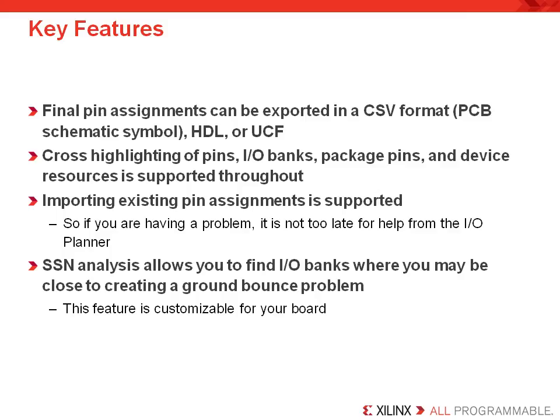And as I have already mentioned, noise analysis helps you to find pin assignments and I/O banks where you may have too many pins of the same I/O standard. This provides you some confidence that you're not creating a problem for yourself with your pin layout after you've done extensive design work.